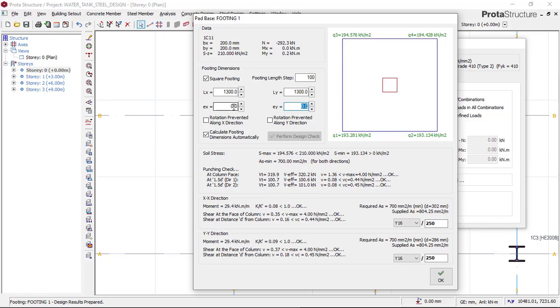footing. Now, if I mistakenly input any value, let me say I input 200, you will see what will happen. This column will tend to shift. So I input 200, you can see that the column has shifted, but it is good to leave this eccentricity as 0. So I'll click back here.